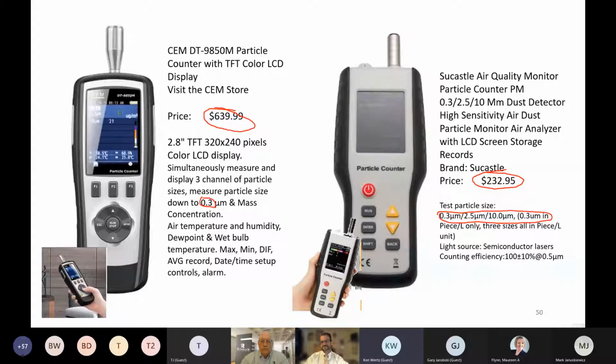Yeah, and Tom and Jeff and I had spoken earlier that this ties in with the importance of knowing what's coming into your building. You have to take outside measurements before you take your inside measurements. You need to have both levels of information. Otherwise, you don't have a baseline to compare against. And like Tom had mentioned, the outdoor air quality changes drastically in a very short time. In addition to the parts per million for particulate level, it's also your CO2 levels. Your CO2 levels do rise and fall just like the particulate level does. So having that understanding of how your building responds to outside, I think, is a critical part.